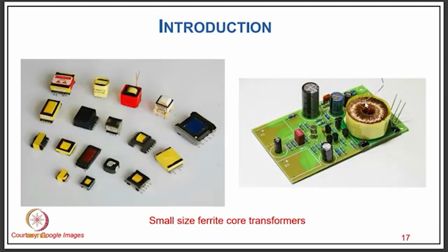There are a lot of transformers for high frequency applications, typically used in power electronics and electronics transformers, which are normally made with a ferrite core, not with laminated steel, because the power is low. Apart from that, when we go for high frequency, the size of the transformer is reduced for the same amount of power. There are plenty of applications of this, and day by day the applications of such high frequency transformers are increasing.